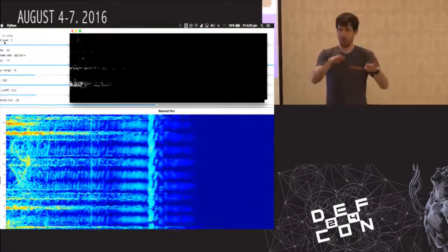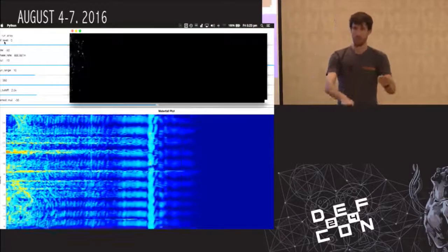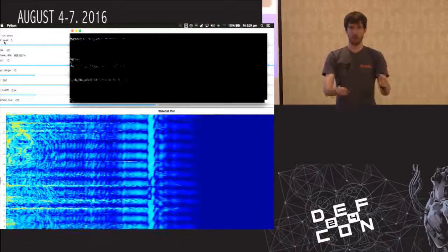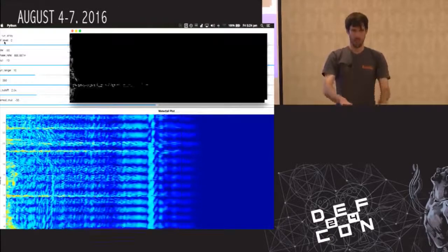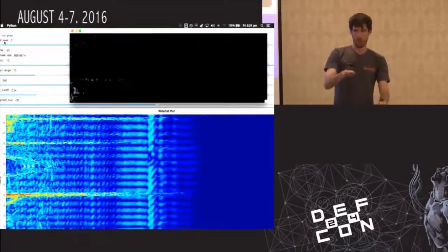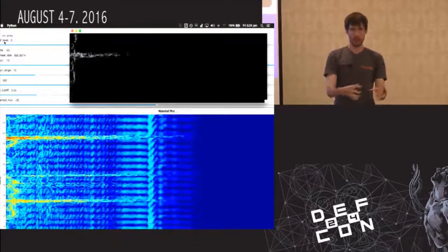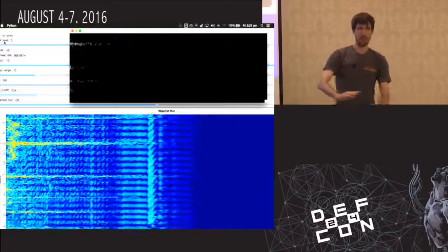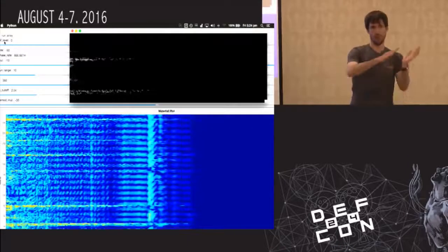And what that's doing is it's changing the delay between the 2 wavefronts that come out of the laptop. So when they come out at the same time, it'll go directly up. But when you offset one, for one to come out a little bit sooner than the other one, you're basically going to add them together as the wavefronts propagate and then beamform it in one particular direction.